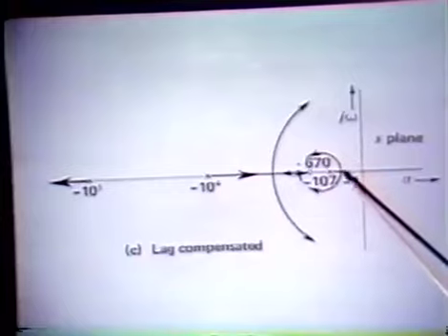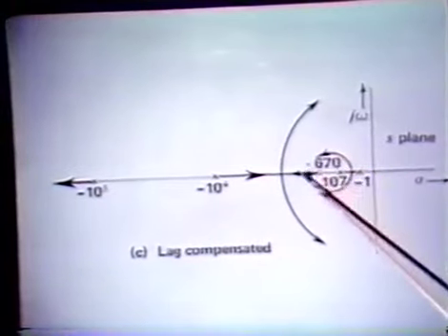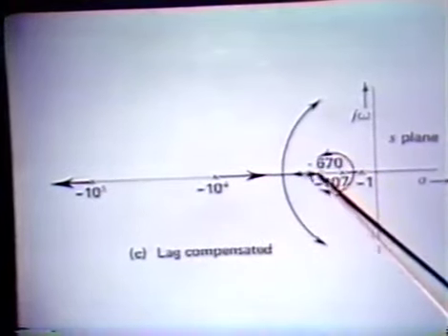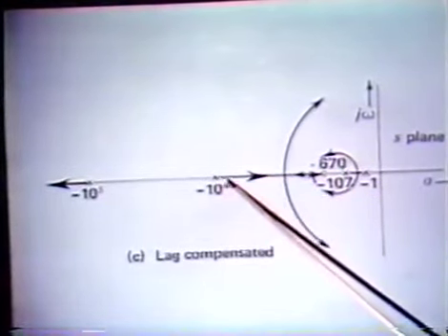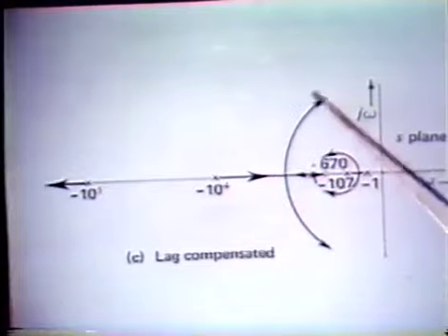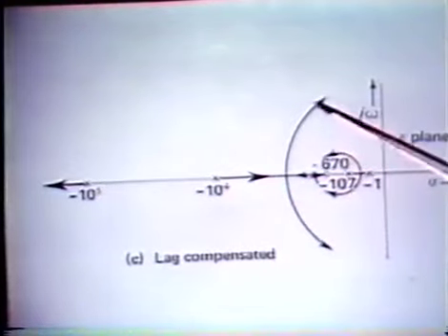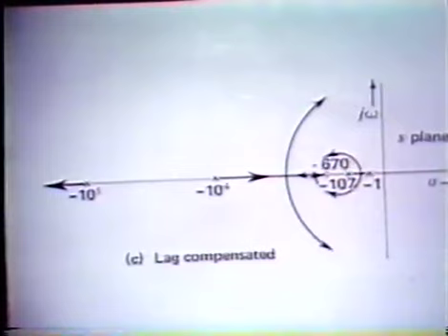We do the root locus diagram. These two branches come together, circle around. One branch heads toward this zero. One out here joins this branch. They then spread off. And the pattern out in here looks very, very much like the uncompensated case.